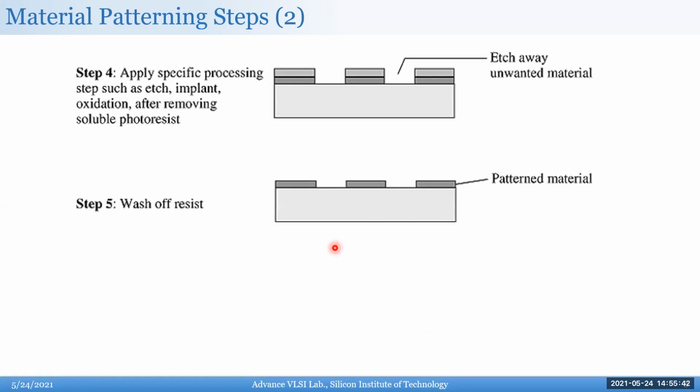Okay, and after that you again remove the photoresist, which is again a selective etching. It's a selective dissolvent, so a solvent meant only for photoresist. You just put that on and spin it, and then all the photoresist is basically gone. Okay.